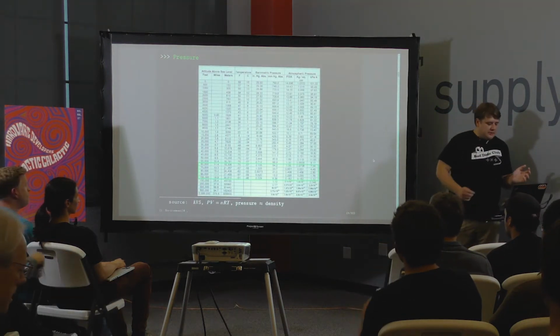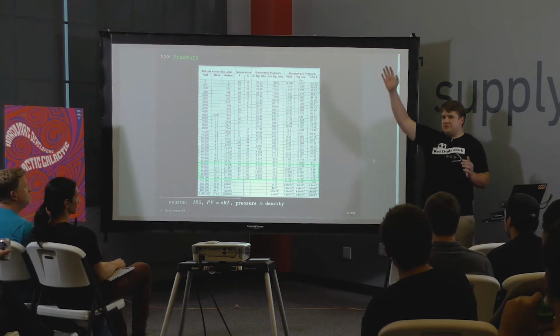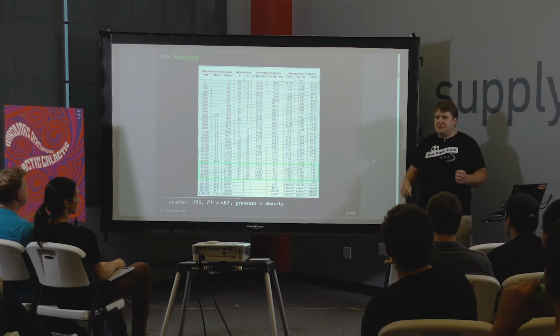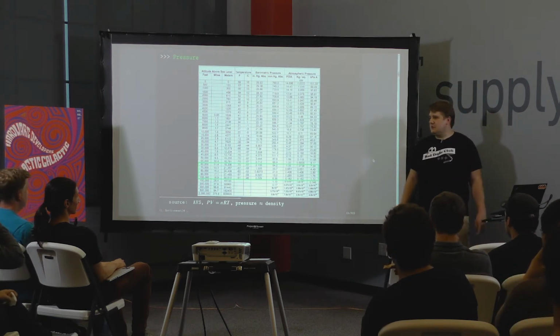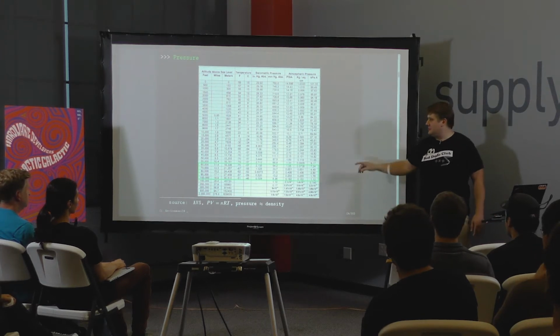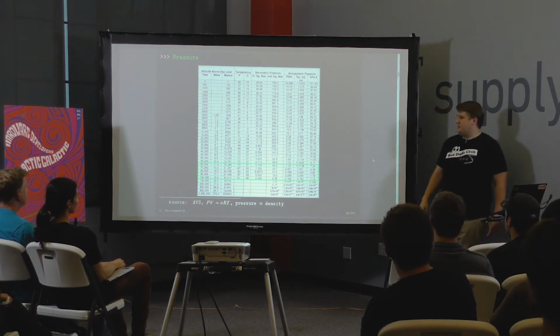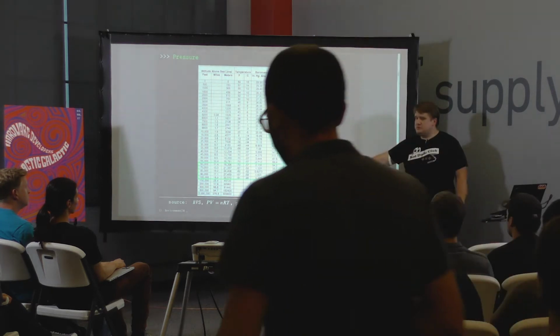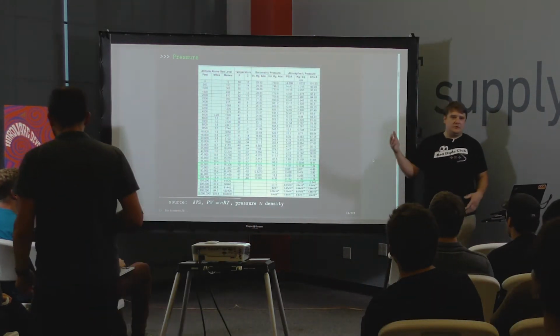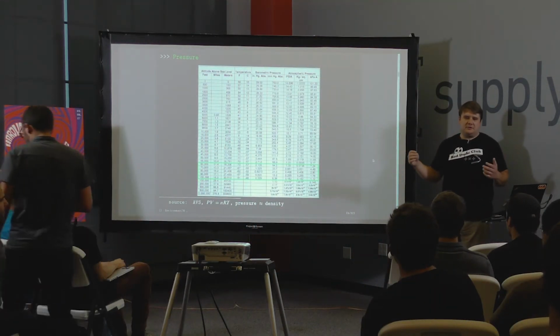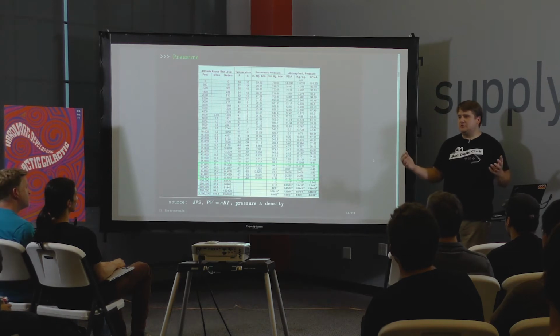All right, so the stratosphere is the region above the troposphere, and typically defined as 60,000 to 150,000 feet. But most of the cool stuff is between 60,000 and 100,000, just because by the time you go above 100,000, you have to have a lot of lift gas and your volume to mass ratio gets crazy.